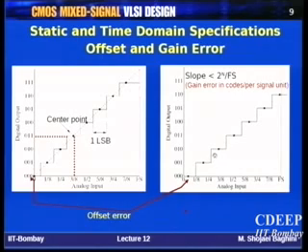When you have a change in these values, the middle values, center points or transition points, you won't get a perfect line again. If you take the envelope of that line, it may not have the same slope, because, for example, you may miss a code here. Therefore, your effective slope definitely won't be 1 bit per 1 LSB. Therefore, the slope will change.